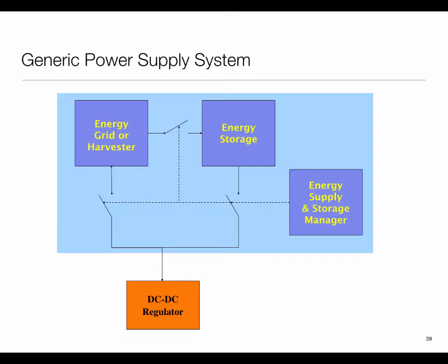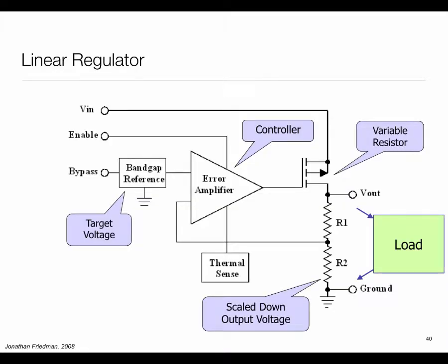So a little bit of the next two slides, a bit of a circuit just to illustrate the point. You'll see very commonly two types of regulators used in embedded systems, and I just want to throw them out to give you a flavor of why they get used. A straightforward type of regulator is what is called a linear regulator, and it's basically an analog circuit.